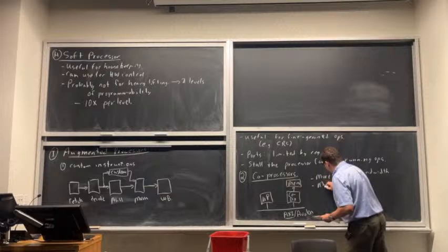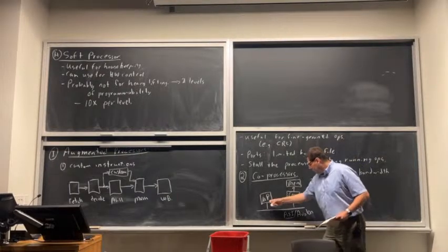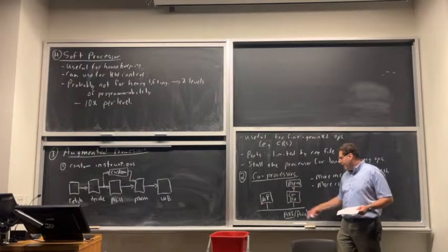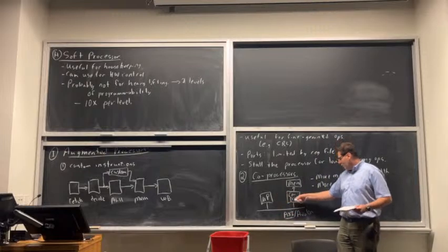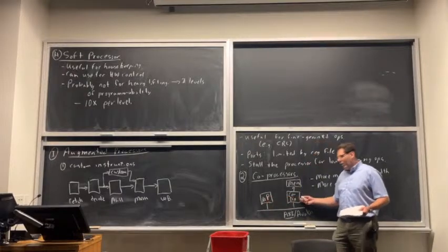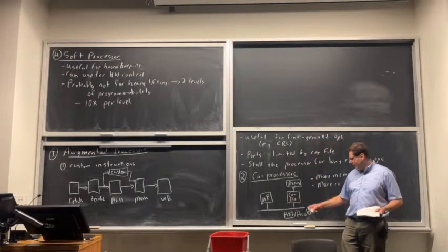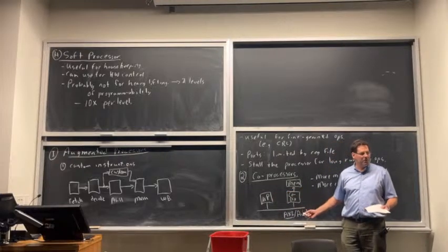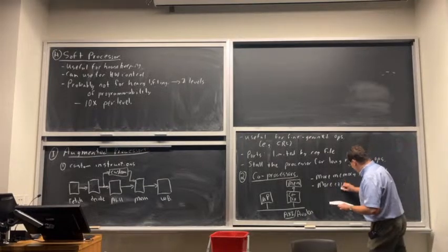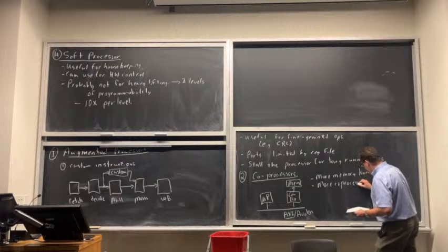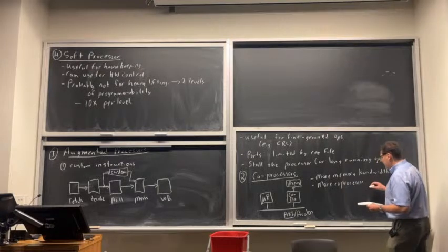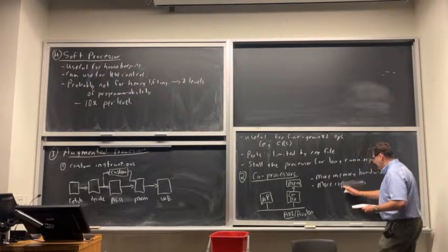We can get more concurrency. Okay, so the processor sending a command to this coprocessor is just it writes to one or maybe a few registers. And then it just keeps going. It doesn't have to wait, right? And the coprocessor, when it's done, it could write back to a register that the processor can read, or more likely the processor just reads some status register, right? So this could interrupt the processor. Processor could read some status register. So there's no reason that one of them has to wait for the other. They can do work independently and just synchronize whenever necessary by reading some registers. Okay, so it's more concurrency.